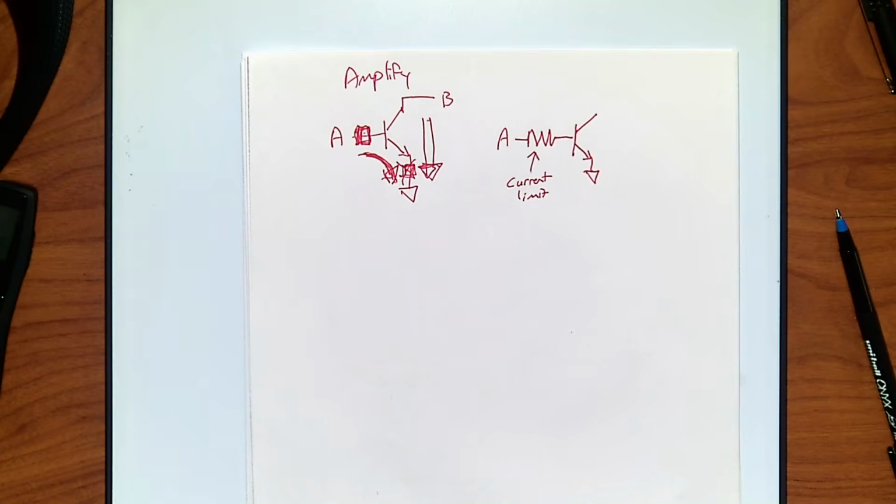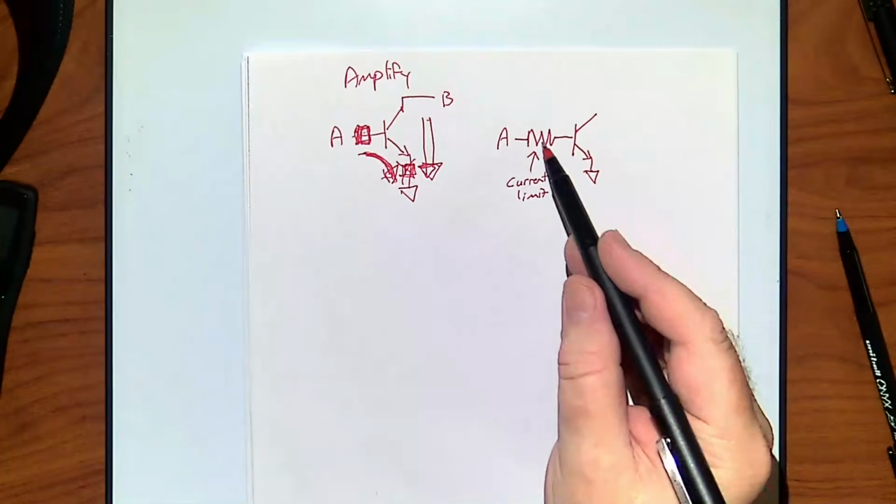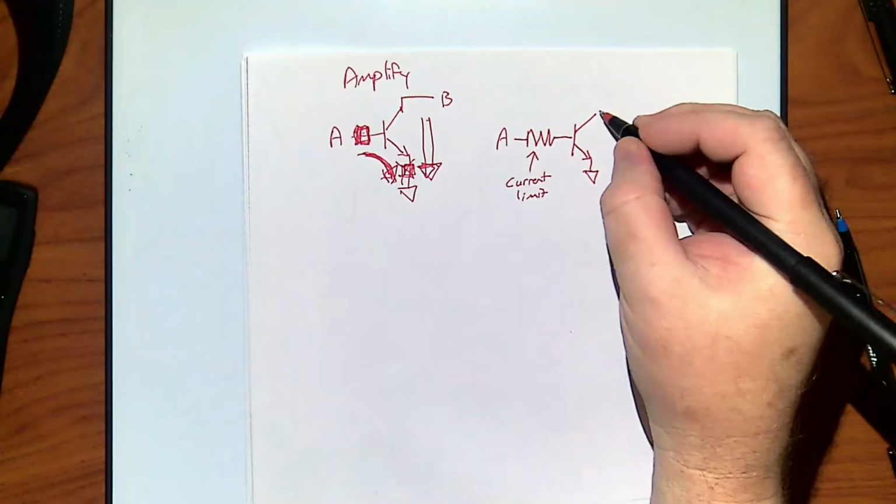Even if it's coming in weak at 4 volts or 3.5 volts, even if it's 2 volts, that's more than enough for that 0.7 volt drop. Remember, a tenth of a volt on this is enough to accelerate that electron to be traveling thousands of miles an hour. It's ridiculous. Electrons are really, really light. It doesn't take a lot of voltage to get those suckers flying once they're up in the conduction band. So we've achieved that with the 0.7 volts. So the resistor in that spot just stops us from burning things out.